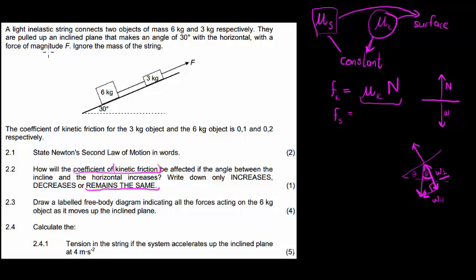So the formula here would simplify to, or be more accurate as, mu k, coefficient of friction, times the portion of the weight that is perpendicular to the surface. So we'll use cos of theta, which is that angle it makes. Okay, so we'll use this idea in the next question. It's only why I'm expanding it a bit now.